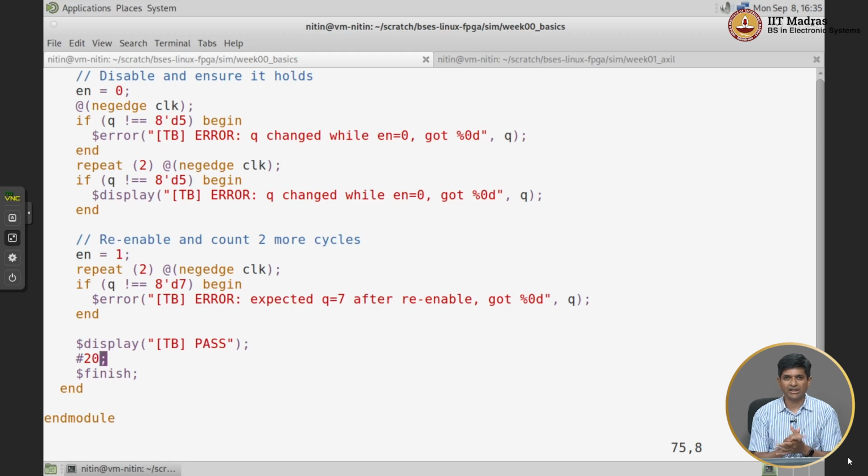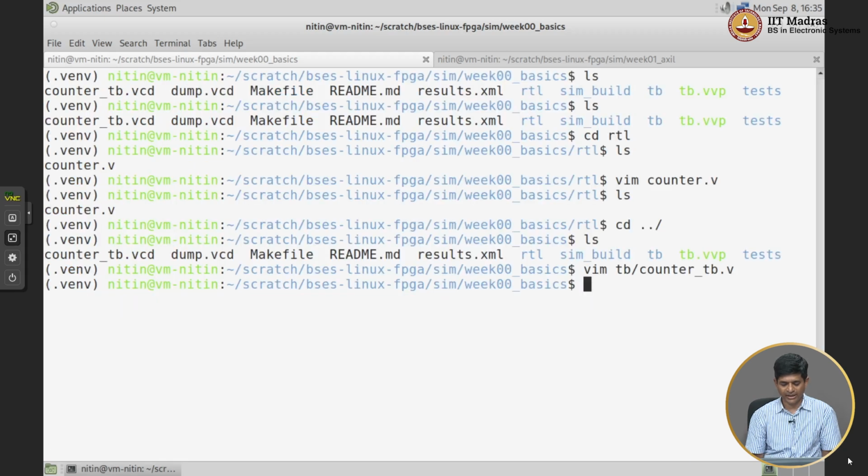I would probably use the iVerilog simulator, add the test bench as well as the code, click simulate and everything is done and I can in fact view the various waveforms and so on. If I was doing this by hand instead, right, I would probably use a command like iVerilog and give the different commands that need to be run in order to actually get the simulation performed.